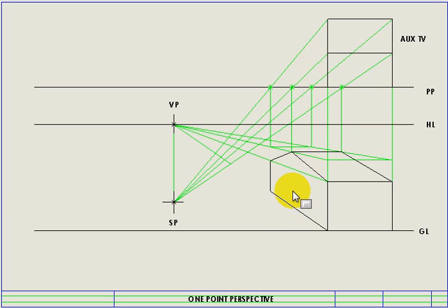I can't really see whether it is permanent or not because my top view doesn't display it and my front view doesn't display it, but I know that from the ground all the way up to my apex of my roof is a nice flat surface. So in this case over here, I'm not going to make that line from this point to this point a solid line.